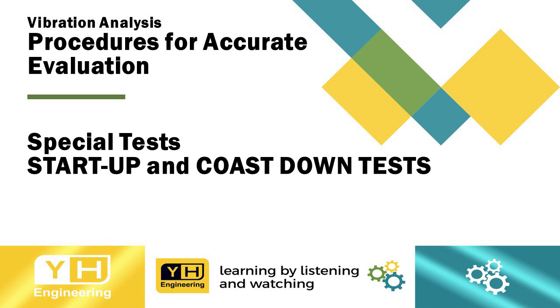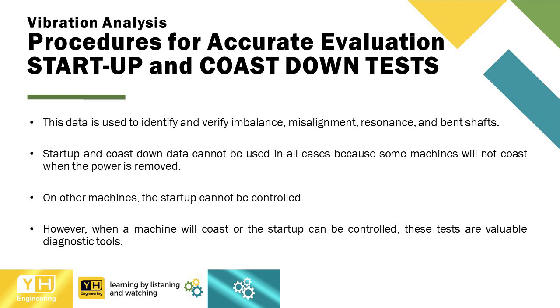Vibration analysis. Procedures for accurate evaluation of machinery condition. Special tests. Startup and coast down tests. This data is used to identify and verify imbalance, misalignment, resonance, and bent shafts.